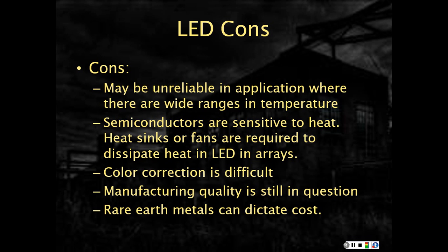The other problem with LEDs is that for a long time color correction has been really difficult. Trying to get really good color rendition off of LEDs has been a trick. We're to the point now where LEDs can rival fluorescence. You can get an LED with a color rendition index of up around 80, but there's still nothing to replace incandescent as far as getting super high color rendition indexes of 90 to 100.